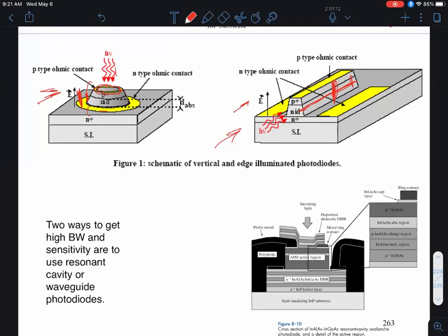Now, the challenge, however, is somewhat of a technological problem, because remember that this structure, although on this PowerPoint looks nice and big, in reality is going to be a tiny cross-sectional device. And very often the issue becomes, you have this optical fiber that comes in, you have to mate that to this tiny side of the waveguide APD type structure, okay? And if you don't mate that properly, there can be losses at the junction of the optical fiber, through which my photons are coming in that I hope to absorb and convert into an electrical output. So mating this optical fiber nicely so that you don't have light losses at this edge is an issue.